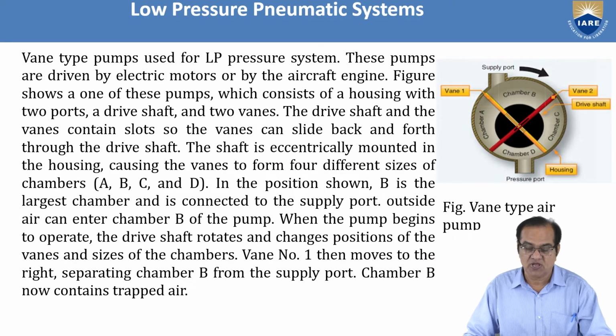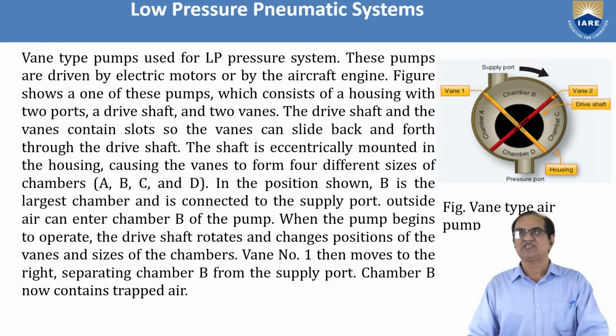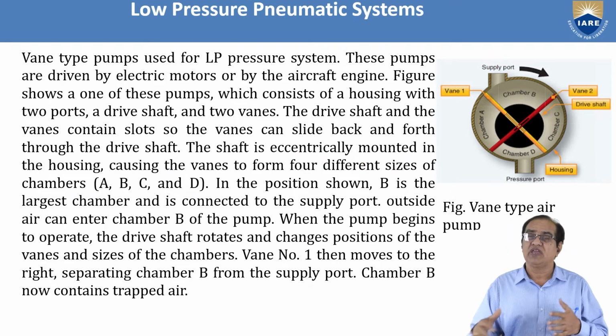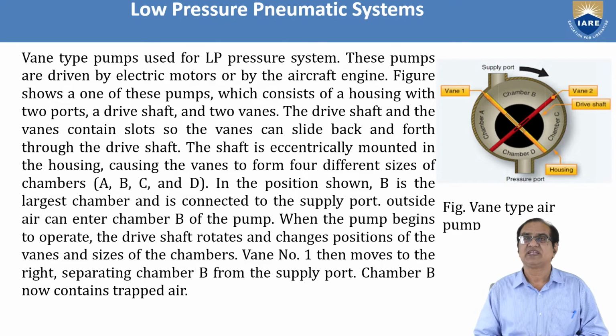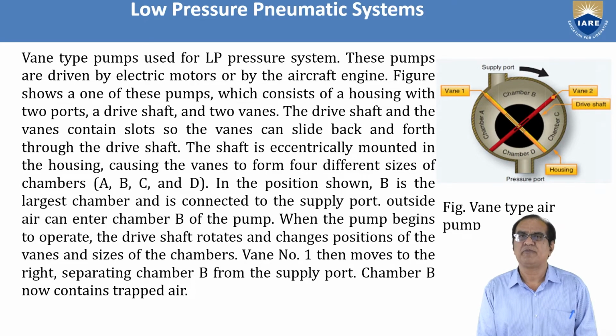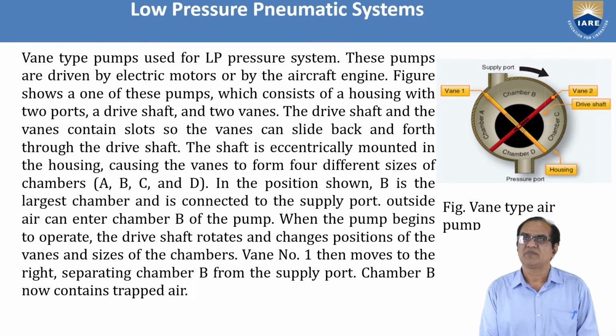Okay, so now the low pressure pneumatic system. Further, if you want very low pressure, a vane type pump is used for the LP pressure system. These pumps are driven by an electric motor or by the aircraft engines.